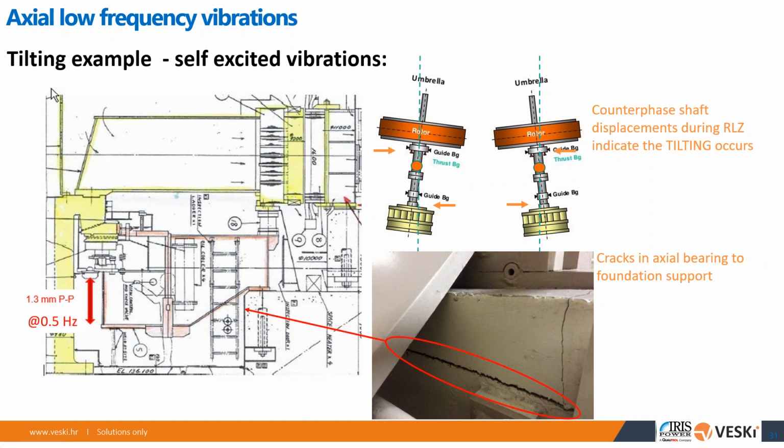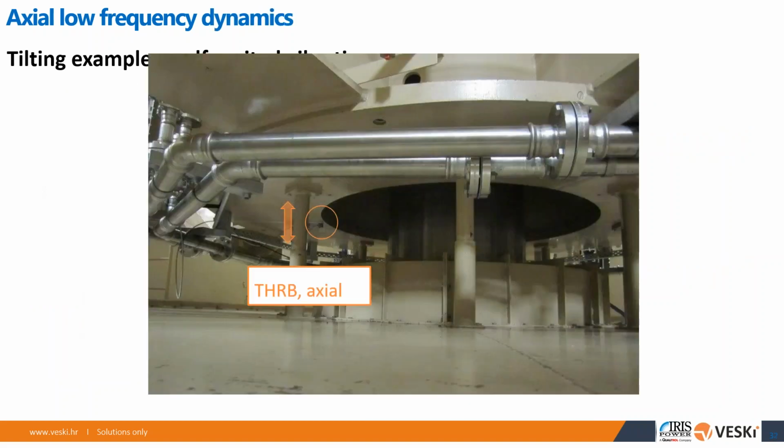And that instability, just because there's a lot of energy from water that cannot be transferred to the turbine, has to be released somewhere. So basically it releases itself as self-excited vibrations of the whole system. And that usually occurs at the lowest frequency of the system, right? So self-exciting vibrations always occur in lower frequencies, right? So this is the example where we put the accelerometer. It's on the bracket, basically monitoring the whole big wobbling, right?